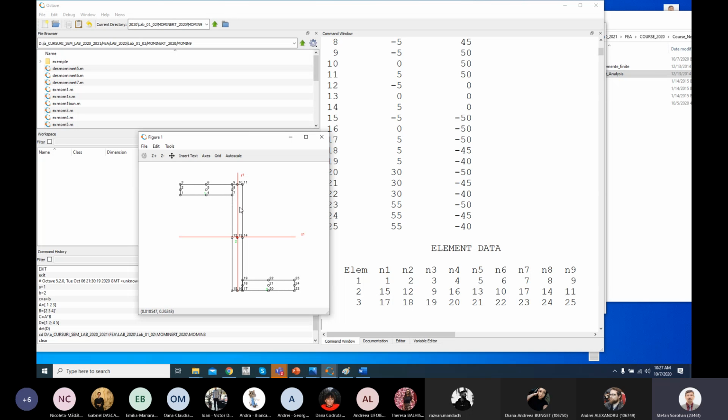This element is defined by 9, so 9 is a common node if you want. You will see later that the correct mesh for a real problem is not good if you have some nodes which are not connected to their neighbor elements.